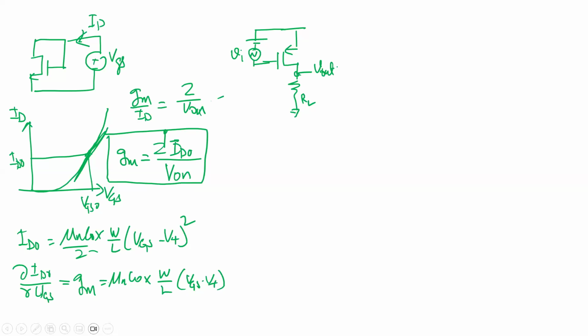And this is a negative gain, so this will be out of phase by 180 degrees, right? Because if this current is going down, the current is increasing here, this will go up. So it's 180 degrees out of phase. Just like the NMOS, PMOS is the same too. Okay, so now if I find out Vout, it is what? Vout is equal to ID times RL, right? And I assume that it is always in saturation. I bias it in such a way that it is in saturation.